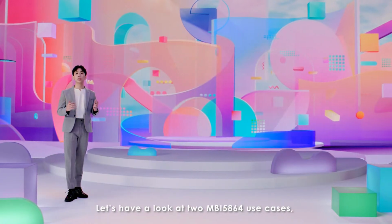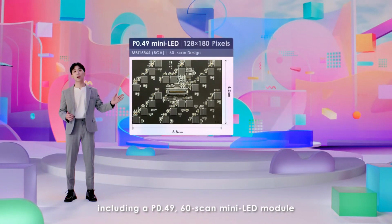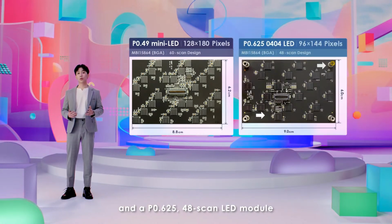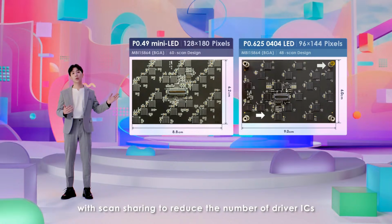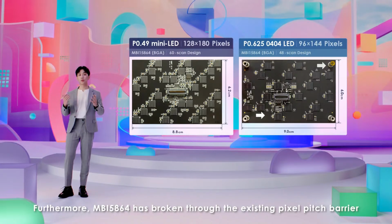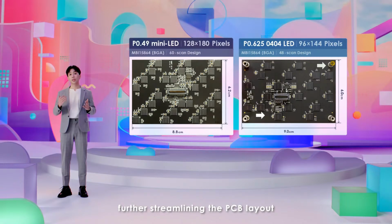Let's have a look at two MBI 5864 use cases, including a P0.49 60-scan mini LED module and a P0.625 48-scan LED module. We can see the modules are tiny as MBI 5864 combines BGA package with scan sharing to reduce the number of driver ICs. Furthermore, MBI 5864 has broken through the existing pixel pitch barrier. It's easy to put it on the back of the P0.49 mini LED module, further streamlining the PCB layout.